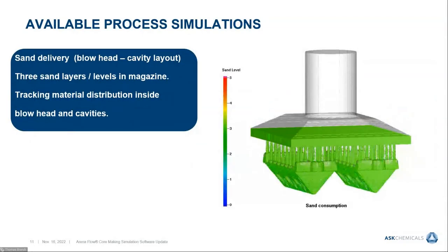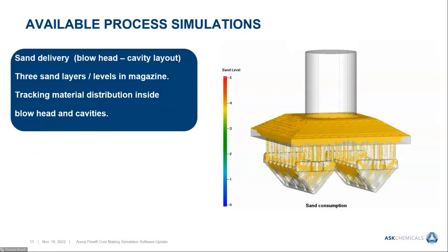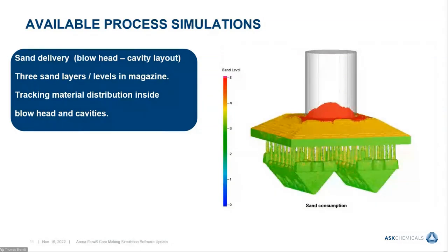In addition to that, we have the ability to model the full setup, sand moving through the magazine into the cavity, looking at how material is distributed through the system. Any potential problems like blow tubes running out of sand or not ideal positioning of cavities.